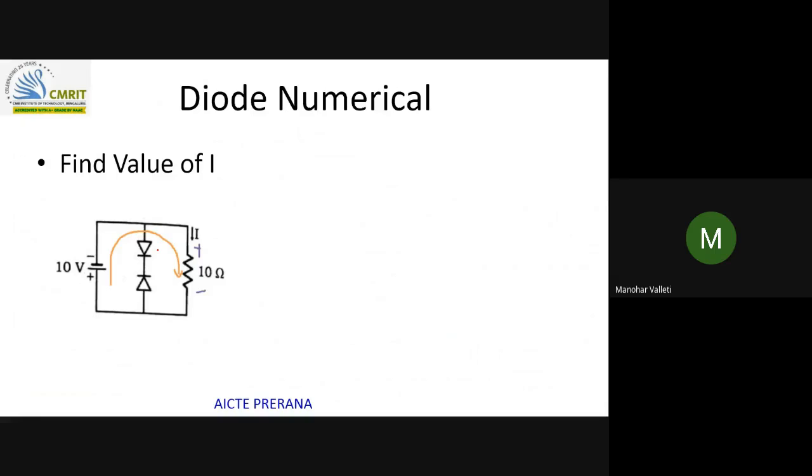But when we are solving the problems, we won't see both terminals of the diode. If any one terminal satisfies the definition of forward bias, then we will say that the diode is forward biased. And one more thing, now in this the diodes were ideal.